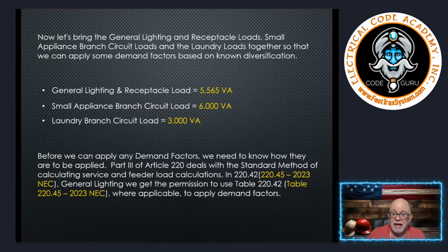Now, whether you use it or not, it's totally up to you. But you have to have the laundry circuit in the standard method for that calculation, because the code tells me I do. Now, again, if it's a multifamily building that has a laundry facility on site, then you have some allowances to not put the laundry receptacle in, because it's available to all the tenants and there's a separate laundry facility.